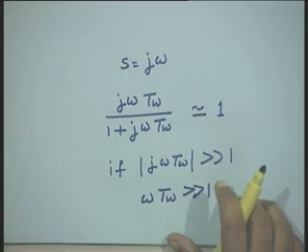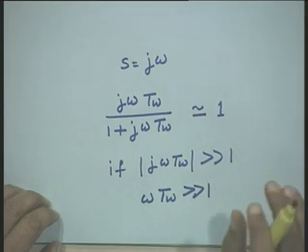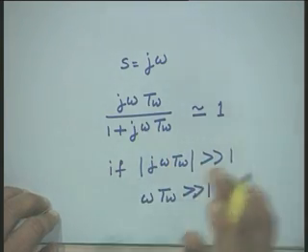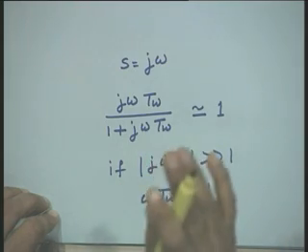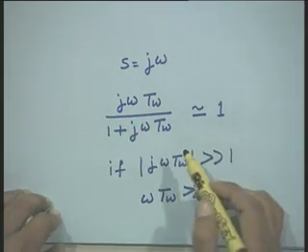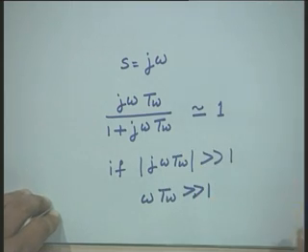At that time also we do not want this PSS to create any problem in terms of variation of terminal voltage. Therefore, when you take T W equal to 10 or around that, the desired characteristic of the washout block is obtained.